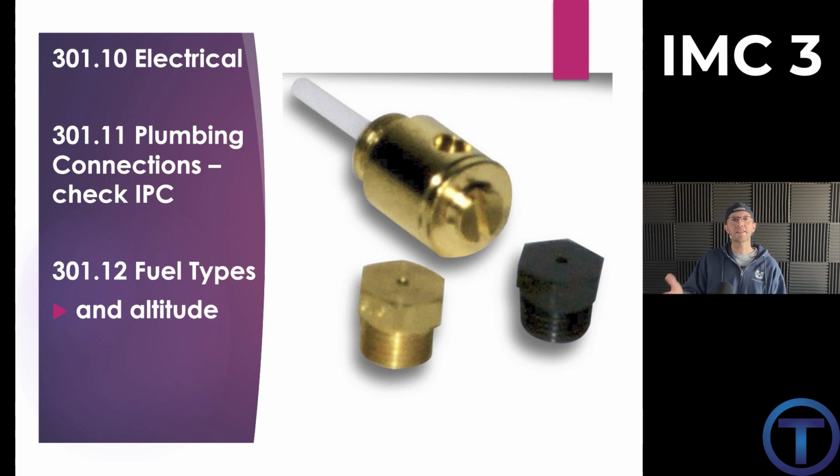Really, any of the appliances that you buy, especially water heaters from a supplier, they're already adjusted for the altitude. But watch for that because it's right on the stickers and it's right on the box. Look on the outside of the box. It'll tell you that it has been adjusted for the altitude. They don't even ship those water heaters that would be rated for sea level to our area because that's dumb. But in the past, we used to have to swap out the orifices. And now they just come ready to roll.